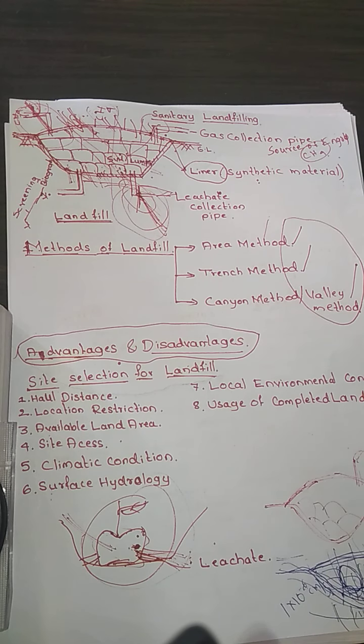Disadvantages: wherever we are going to have this particular landfill, the land rates are going to be reduced, and if it is not managed properly, then it is going to create hazardous conditions for the people who are going to live in the surrounding areas. Also it is going to create groundwater contamination if we don't maintain the sanitary landfilling correctly.